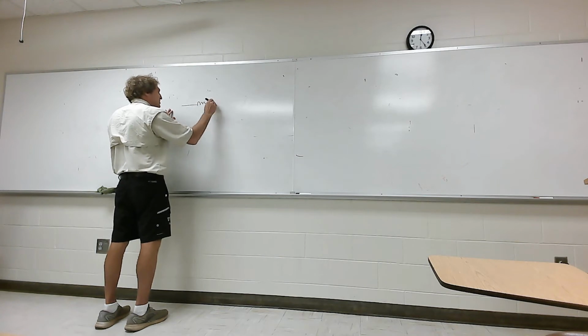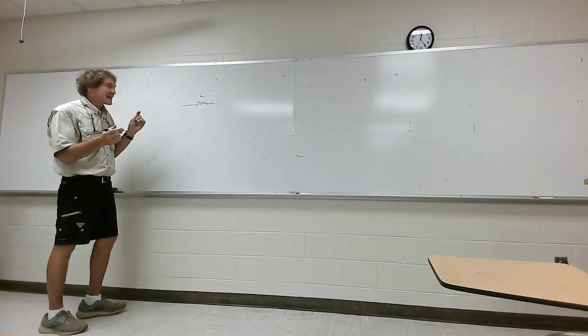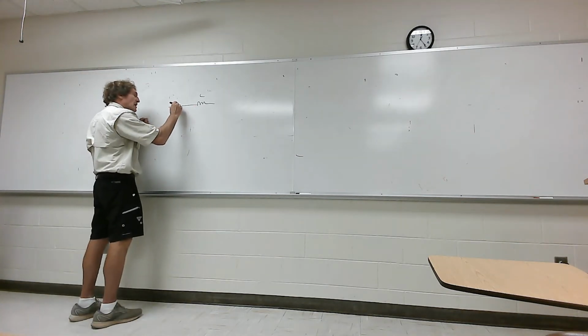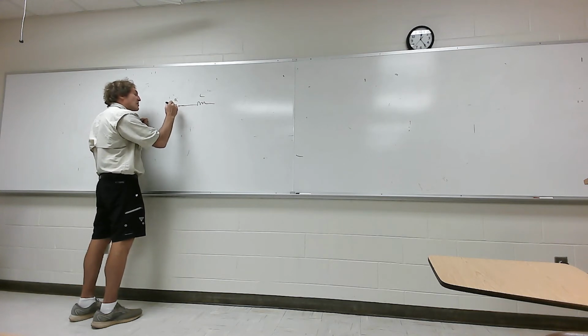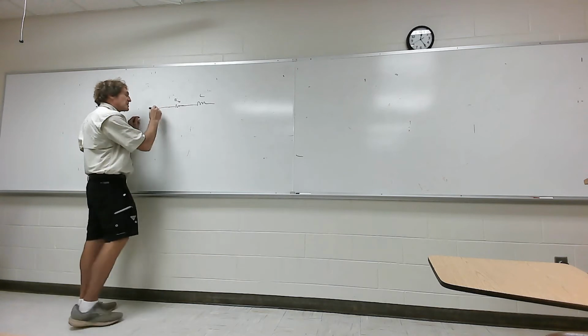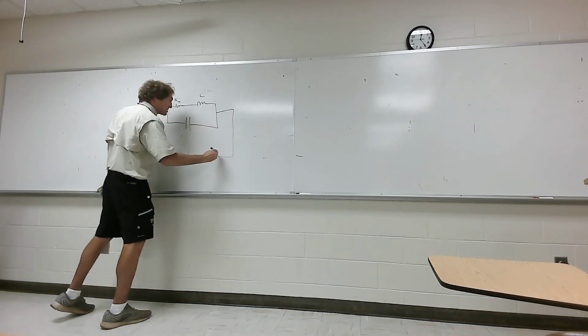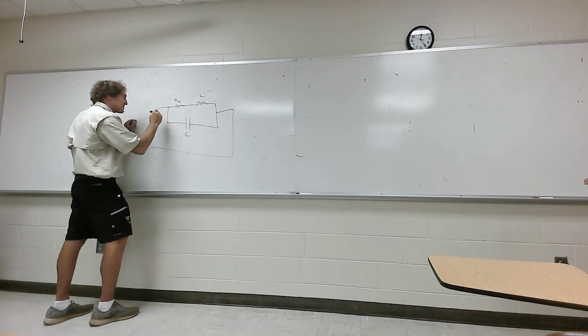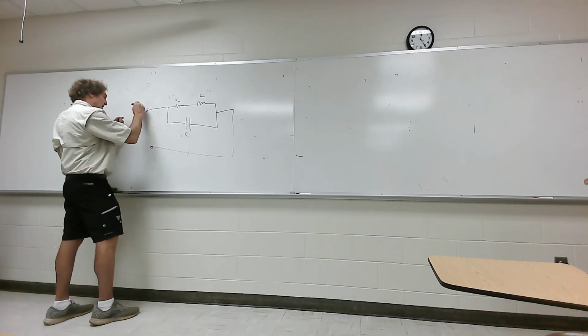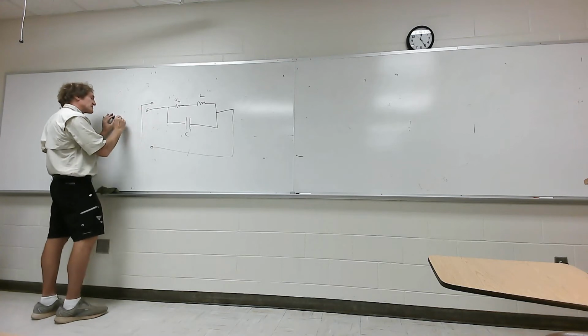You're always going to start with an inductor. That's the value. It's got to have some inherent resistance of the wire. I'll just call this R. It's really R of the wire, RW. Then you're going to have parasitic capacitance that you don't like across there. And this is a correct model for an inductor's impedance at high frequency.